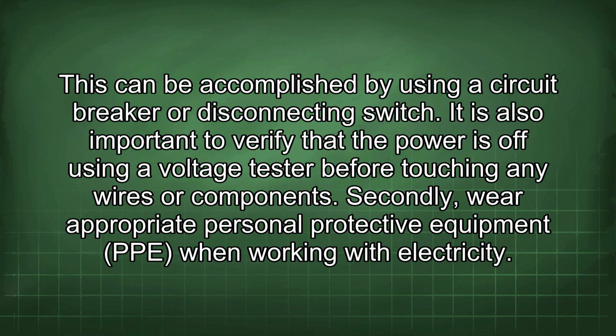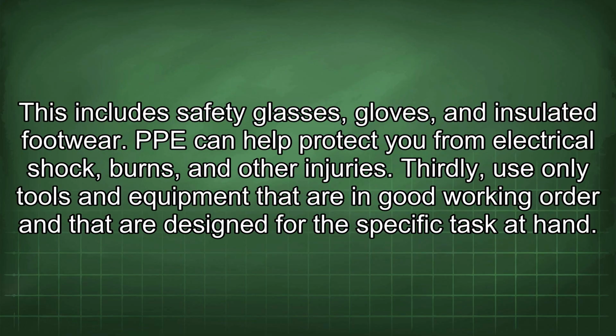It is also important to verify that the power is off using a voltage tester before touching any wires or components. Secondly, wear appropriate personal protective equipment (PPE) when working with electricity. This includes safety glasses, gloves, and insulated footwear. PPE can help protect you from electrical shock, burns, and other injuries.